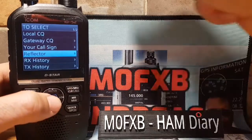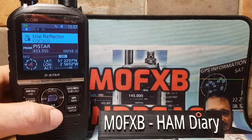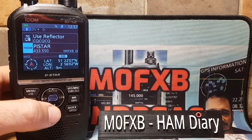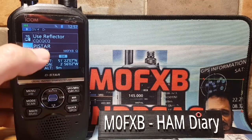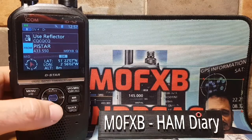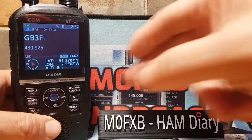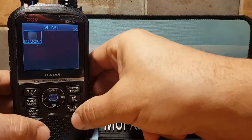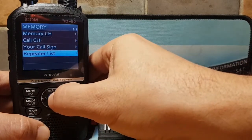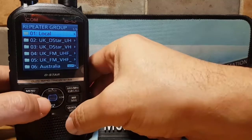Use reflector. If you want a repeater, you want to be selecting use reflector on your hotspot. If you want to actually select your hotspot, which you need to enter, you need to go to the bottom here, Pi-Star, and click, and then you need to add your repeater. Now to add your repeater, you have to come out of DR mode and go over, push a menu thing here and go to the right, and then you go to memory, and then you go repeater list, and then this is where you would add it. So I've got videos dedicated to that.